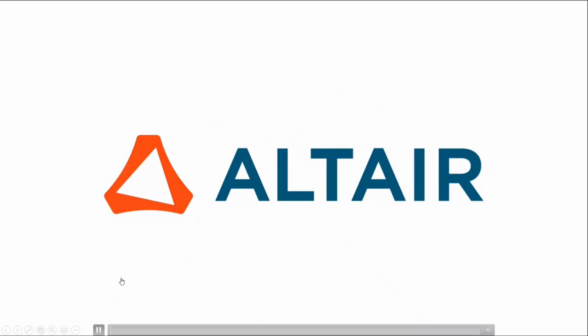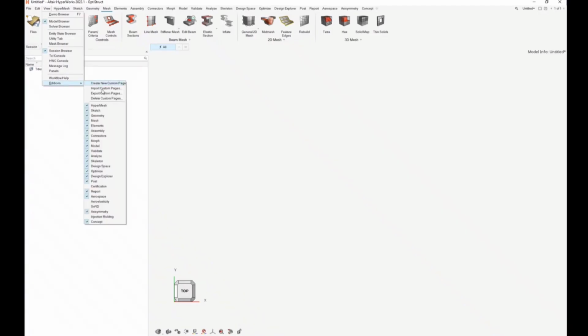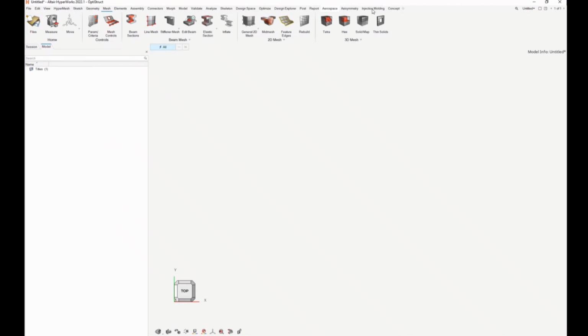And for this one, I have a bit of a longer video because there are a few more steps, and it's actually also a bit of a bigger model. So some steps are taking a few seconds. First thing, you need to enable the injection molding ribbon, but that's very straightforward. You go to view, ribbons, injection molding, and there you go.